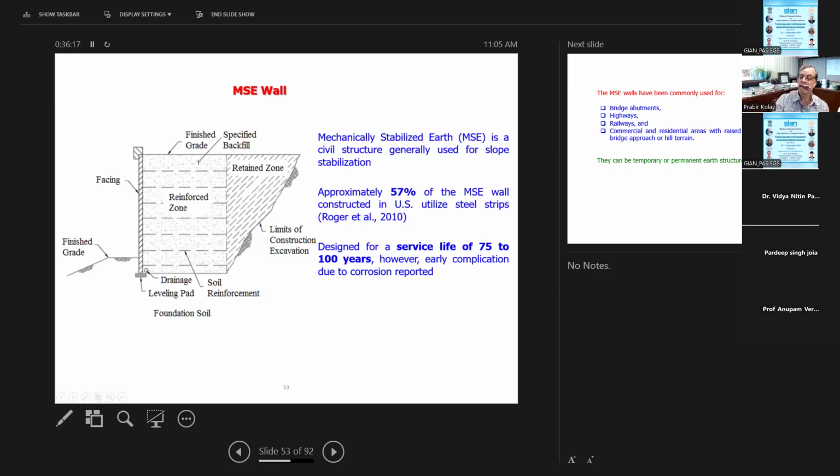Doing this design consideration of the retaining wall. So we need to check, as I mentioned, the conventional retaining wall. We do the external stability analysis to find out the factor of safety because of the lateral load, how much is it, whether it's going to overturn or whether the retaining wall is going to slide, or is there bearing capacity failure.